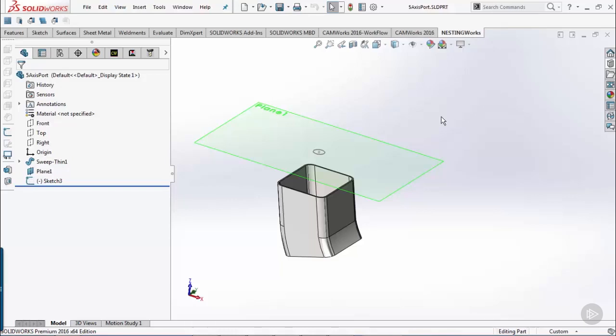The second portion of the 4 and 5 axis lesson we're going to take a look at is doing some internal port machining on this shape you see on the screen. Now, with 5 axis machining, there are lots of different variations on how, when, and why you want to program something. What we're going to go over today is just a really simple selection of taking a ball end mill and machining the inside of this shape.